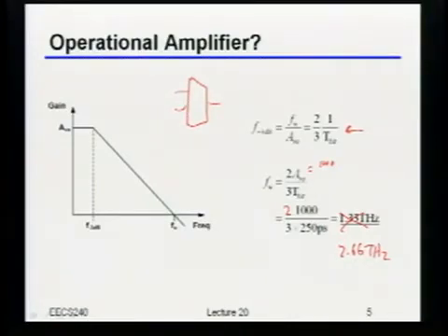If you remember from your plots, up at the really high voltages, your FT was about 120-ish gigahertz or so. Obviously, you're at a factor of 10 over the FT, so no way in hell that transistor is actually going to give you any gain at that point. Now, just in case you think, well, I gave you a 90 nanometer process, and maybe you could do this in a 22 nanometer process and that'll save you. Sorry, FT for those is also about a couple hundred gigahertz. So not going to happen. The bottom line is, no way in heck you can do this with something like an OTA.